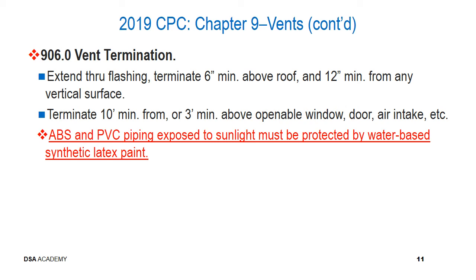And if you see something besides a water-based synthetic paint, you can defer to one of the previous chapters that also permitted 1.02 millimeter tape covering. But again, these details are going to be approved by the design professionals and clarified and detailed on the plans.